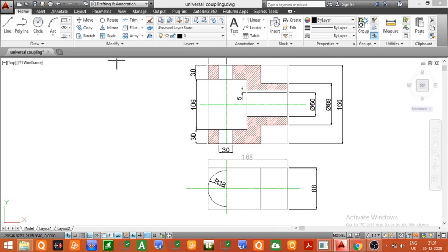After drawing this line, we will join these points, and the next is to be joined this. Students, again I am repeating: first project this point, and it will be drawn as a straight line in the top view of width 88 mm. In the second step, project this corner point, and it will be visible as a straight line of width 88 mm. And finally complete this rectangle.